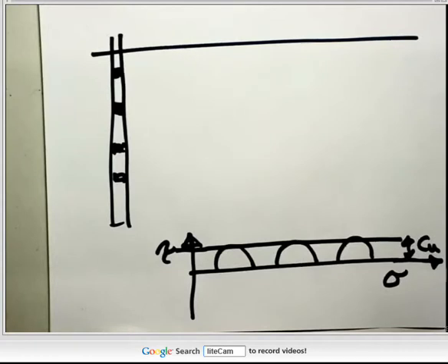This example is a good approximation for a heavily over-consolidated soil horizon, where because you're on an unload-reload line, due to the stress history of the soil, the void ratio is fairly constant with depth. So this might be applicable to construction on over-consolidated clay like London clay, Oxford clay, Gault clay, which are present in many parts of the south of this country.